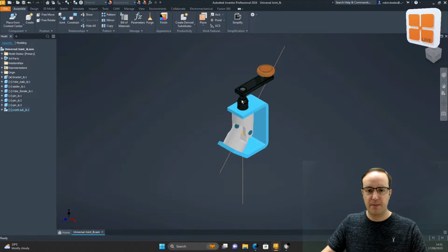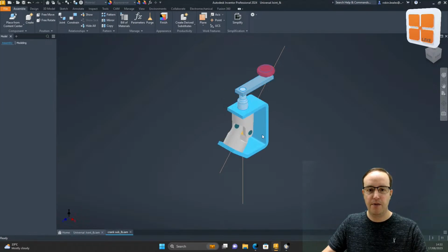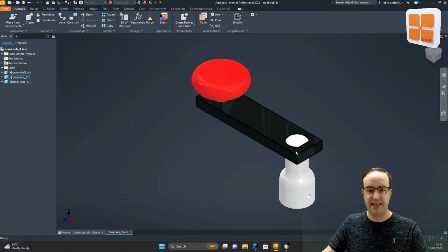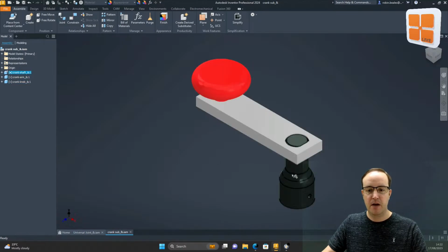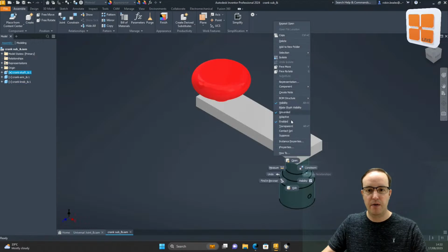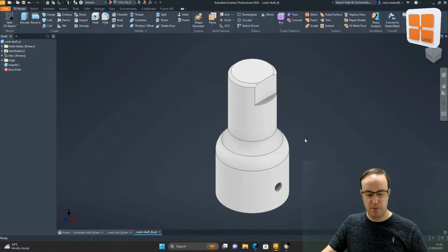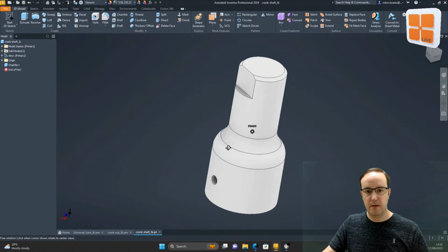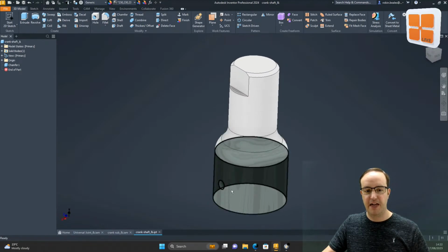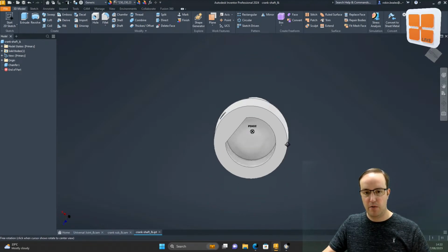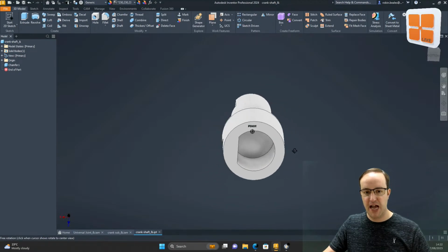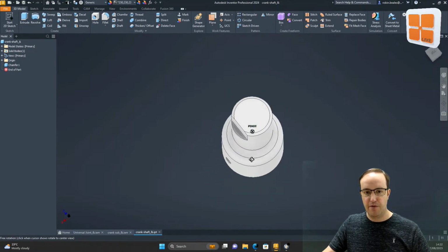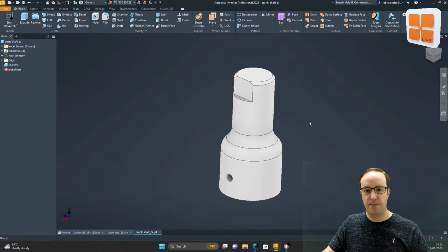So what I'm going to do is drill down to this component. I'm going to right click and open this sub-assembly to show you that it is an assembly in its own right. And I'm going to right click and open this individual component here. So in here we've got a number of different things. We've got a hole, we've obviously got a revolve that's been made at some point, maybe a shell at the bottom here, certainly a couple of fillets and some information at the top.